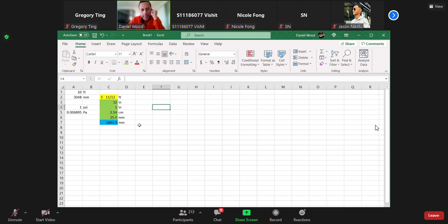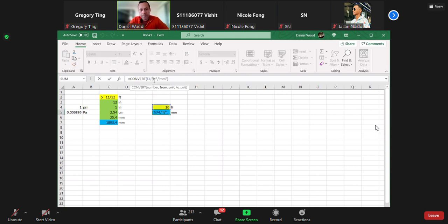Okay, for now, so you can see I've gone from feet to millimeters here. The other thing that I can do is use the convert function. I'll just drag this calculation over to the middle so you can all see it. In this case, my input is my feet, my output is millimeters. So that's where I enter a number. My conversion is here. This is an inbuilt function within Excel, called upon using the convert syntax.